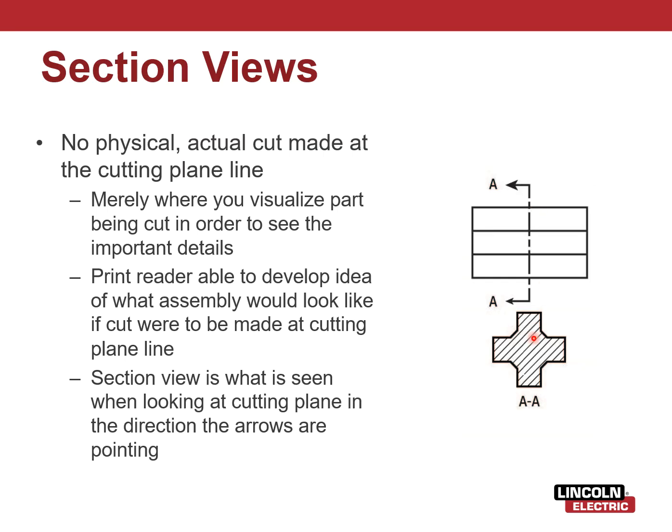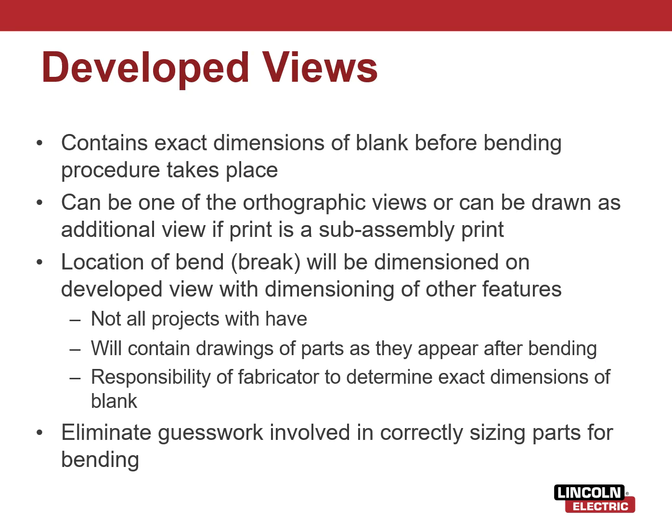So you're going 90 degrees off and looking at this line right here, all right? This does not tell you to actually cut the part, okay? This is not like a weld symbol or something where it's telling you what to do with the material. This is just to help visualize that section of the part, okay? So that's what a section view is.